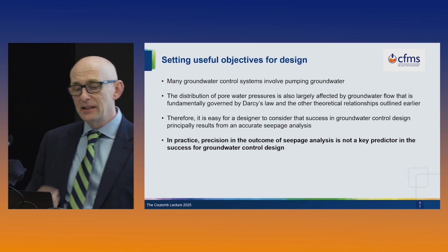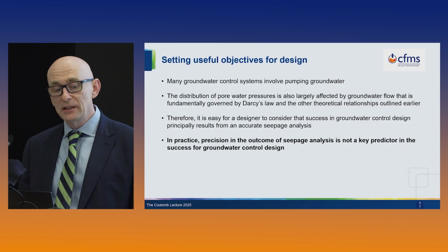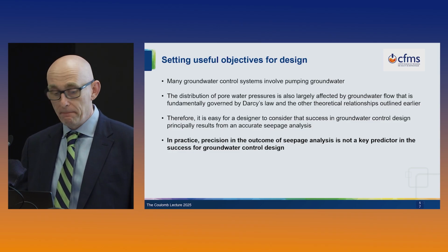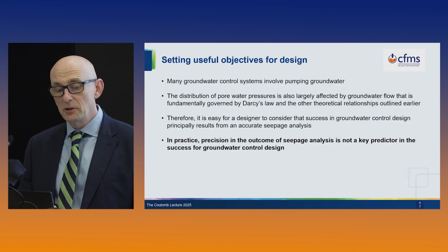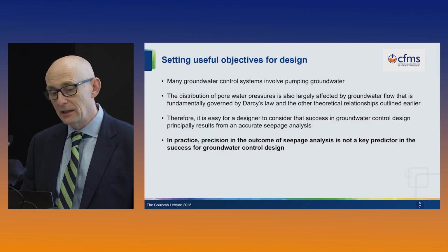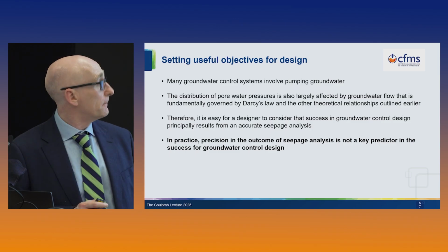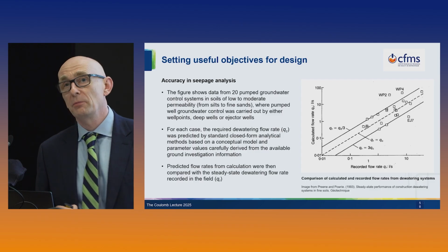So it's easy for a designer to consider that success in ground control design principally results from success in seepage analysis. That an accurate seepage analysis will give you a good design. And I don't think that's the case. That generally speaking, precision in the outcome of seepage analysis is not a key predictor in the success for ground control design. And that's quite a strong statement, but I want to share with you how I've come to that conclusion.